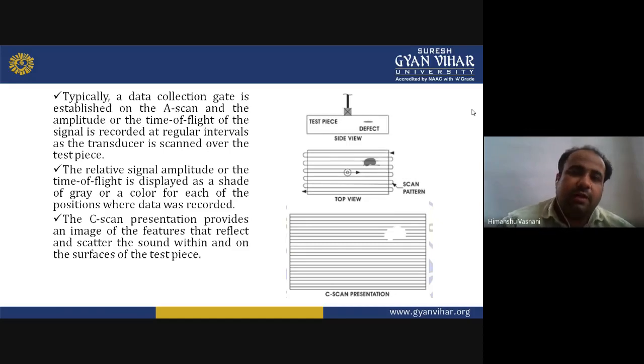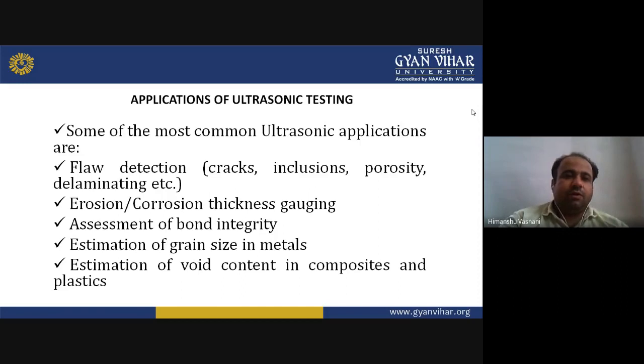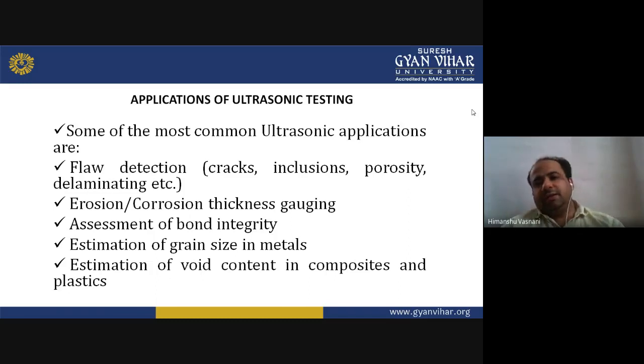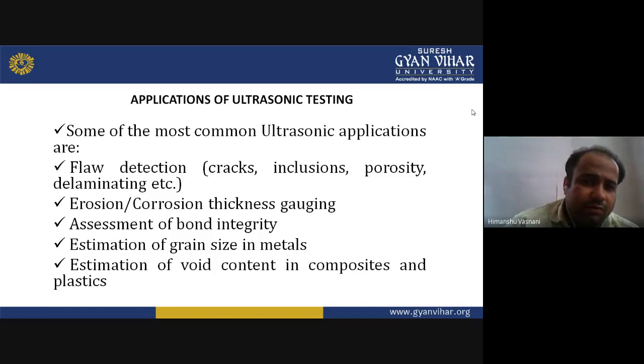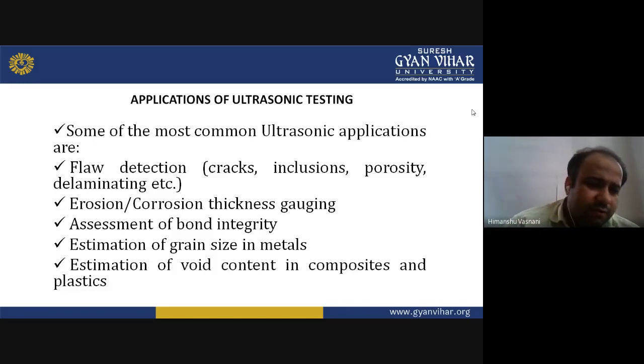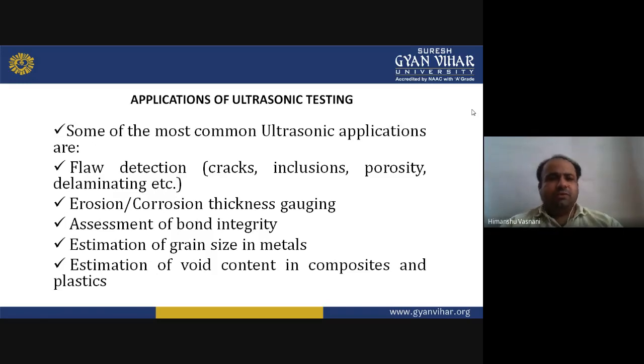This is how they help you to find out the defect, or the location of the discontinuity. In ultrasonic testing, applications most commonly include detection of cracks, inclusions, porosity, delamination, erosion and corrosion, thickness gauging, assessment of bond integrity, estimation of grain size in metals, or estimation of void content in composites and plastics. So these are some